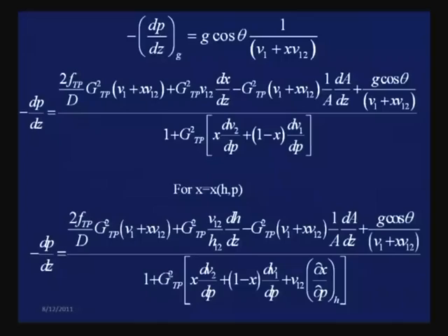Okay. So, we find that if we do it, then finally the expression of pressure gradient has the frictional pressure gradient. If you compare the two, it has the acceleration pressure gradient due to area change, it has the gravitational component, and along with this it also has one particular term which shows how enthalpy changes with dz.